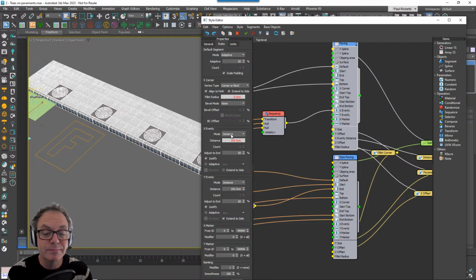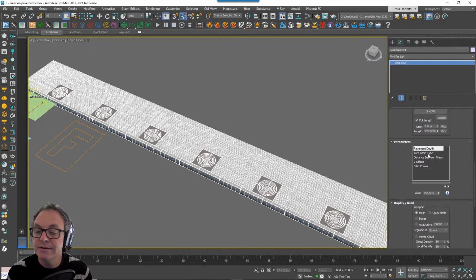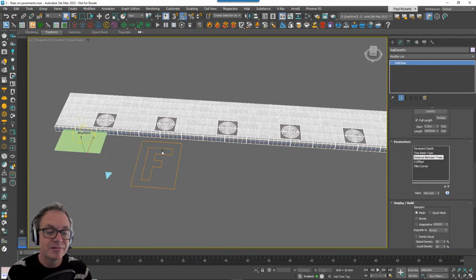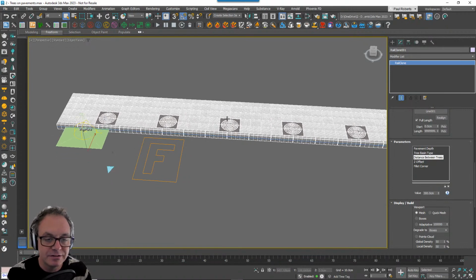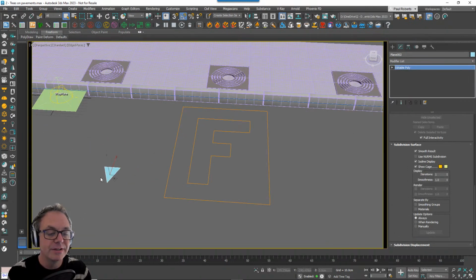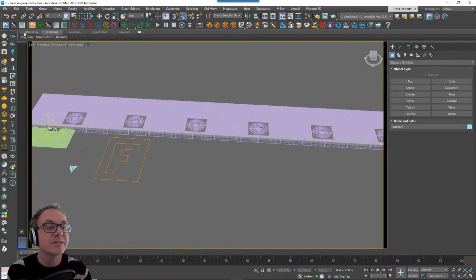So it's in distance mode. I think it's 300 centimeters, and the adjust to end is 50%. It's in justify. Okay, just making a mental note of that. And the distance between trees is 300. Okay. So what I'm going to do basically is to create another RailClone style that uses those same settings, and instead of distributing this quite high poly geometry here, I'm just going to distribute this triangle. And I'm going to use that triangle as a marker in Forest Pack to place objects on. So you could kind of do this in one style and have a switch between the geometry, but just for ease, I'll do it as a second style.